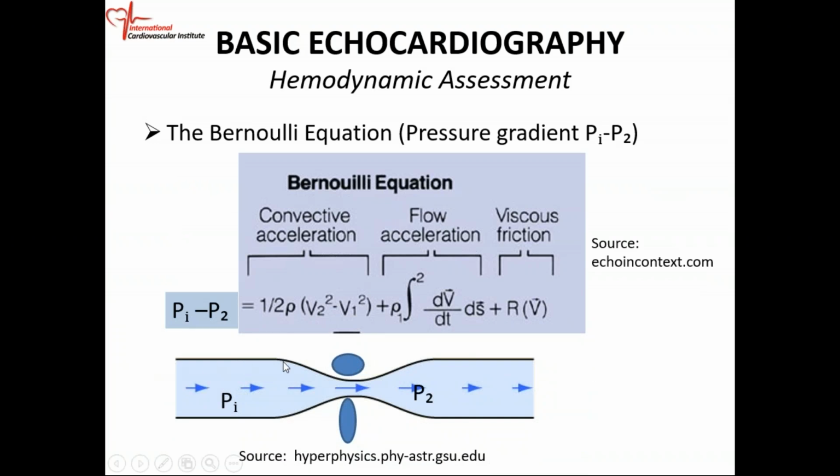If you look at this as a pipe, and you have any fluid flowing in this circuit, the flow at this point is equal to the flow at that point. The flow is the same. The gradient is different, the pressures are different, the velocities are different, but the flow is the same.